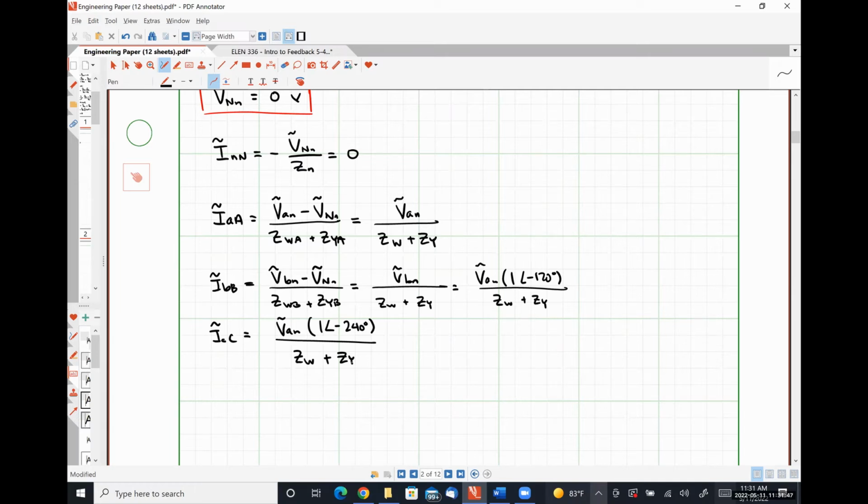In a residential area, typically what would happen is that each street will all be connected to a single phase off of your 3-phase transformer. So street A would be connected between the A phase and the neutral, street B would be between the B phase and the neutral, street C would be between the C phase and the neutral, with the hope that power consumption on average will roughly be balanced